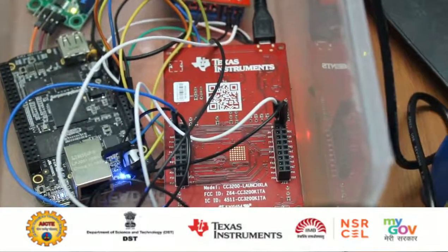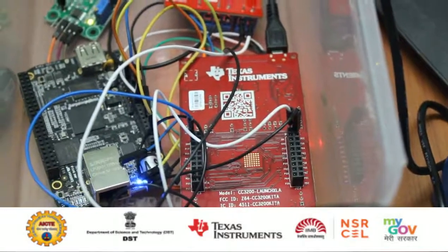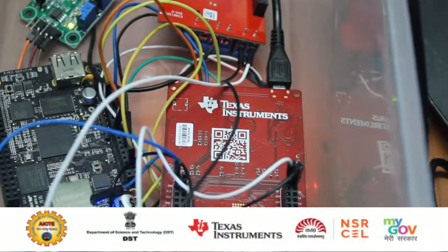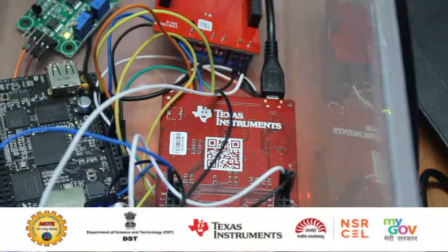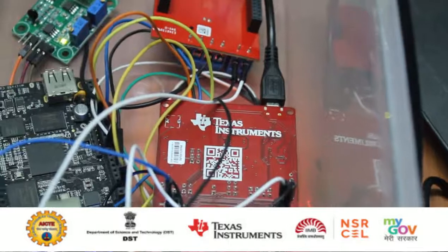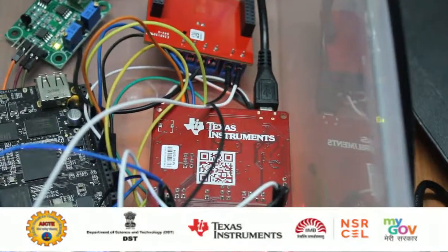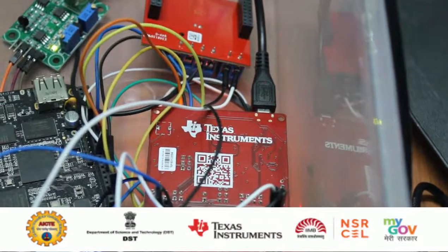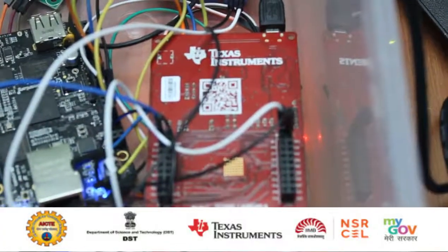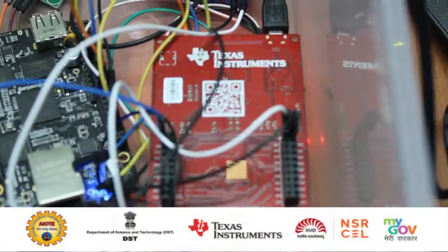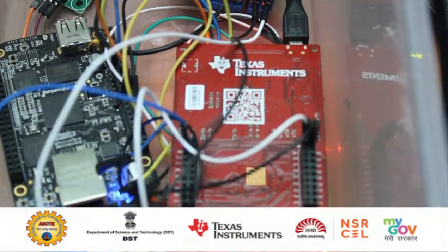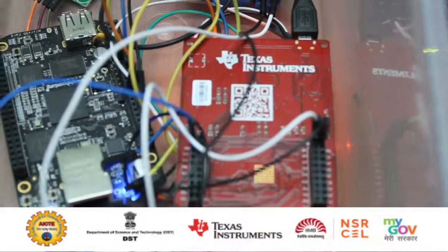Let's talk about the brain of the process, which is basically a controller. The controller reads the sensor values and computes the data, taking the average of it to minimize the error. For the further process, it regulates the motor driver. Another question may arise: why are we using a microprocessor? If a farmer has a large area of land, we can have multiple controllers over the large area, and the signals from the multiple microcontrollers are gathered by the microprocessor. The microprocessor controls all the microcontrollers, computes the data and sends it to the cloud.